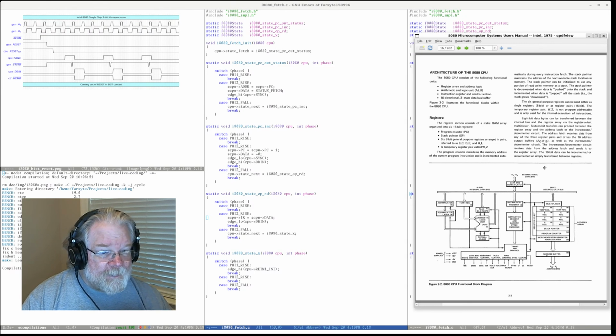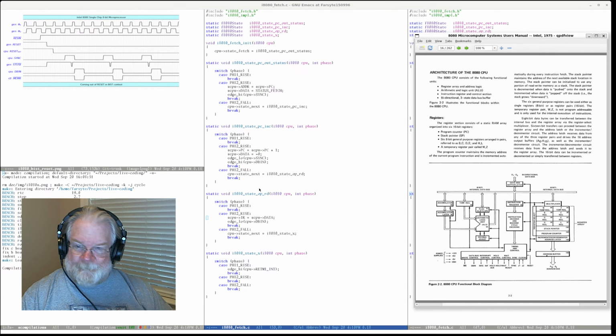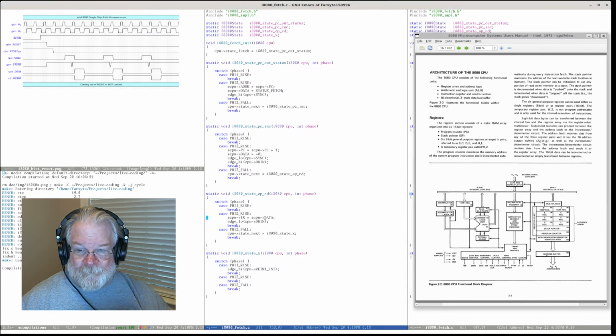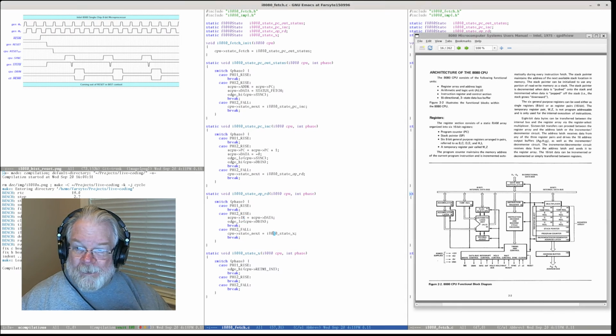If I look here, yes, instruction register. So during this state op read, we have data coming in on the data bus from a memory. I am going to take it from data and put it in IR, and that will drive our logic elsewhere. For now, we're going to ignore it other than print something.